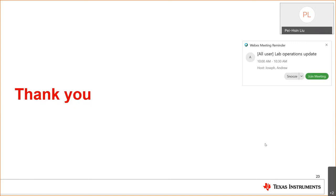Okay, thanks, Tej. Let me elaborate with additional information on this question. Especially for SiC FET, the DVDT is high, right? So to ensure that the switch can turn on and off with known states, the pull down capability of the controller needs to be strong enough. If we take the UCC28C4x family, the pull down is usually 2 times stronger than the pull up. So when the switch node goes high, and there's the CGD charge current from the drain to the gate, this low impedance pull down can ensure that there's no additional turn-on event during that high DVDT event.